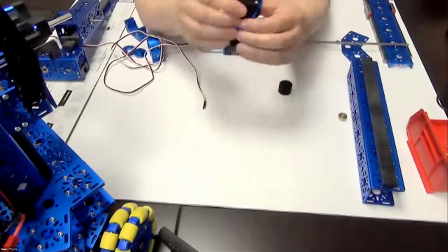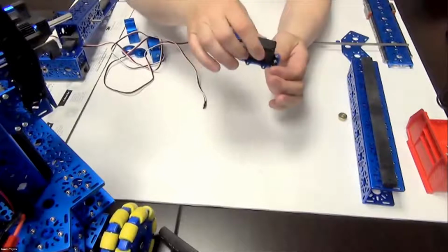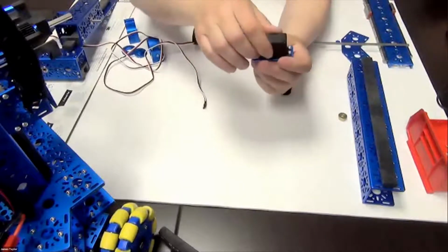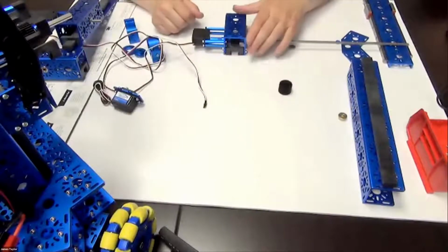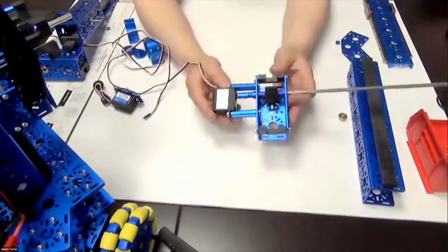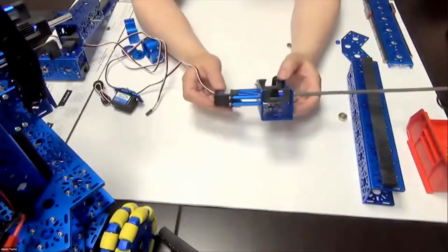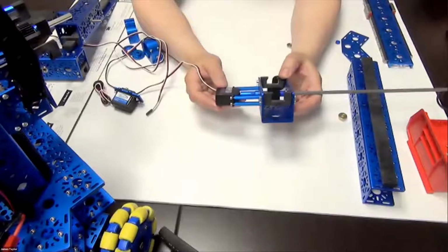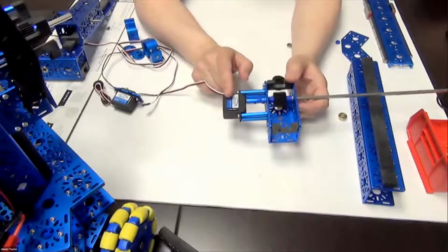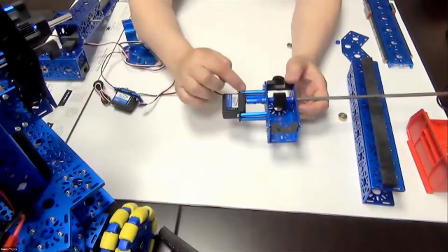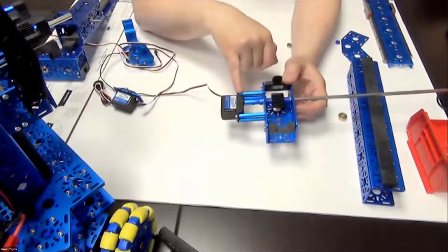So the motor doesn't twist, it has some bracket, because if we don't, what happens is that when the motor is doing radial movement, it can begin to torque and twist out of the system. To show you a sample of that, that's why I had these up here before. These were ones that we had a student in here trying to build, and what he did when he mounted these mechanisms was, there's your servo motor, but he didn't use the frame. He just used standoffs directly to try to get that distance.